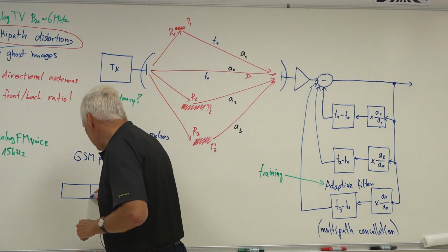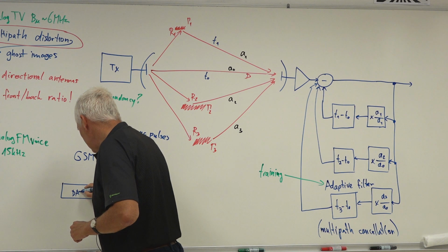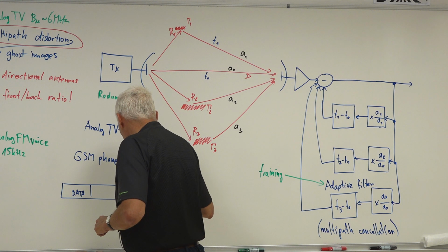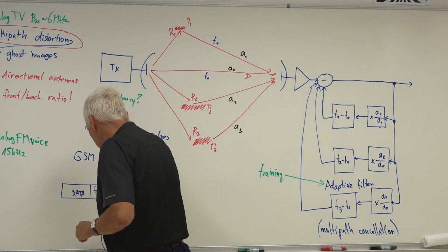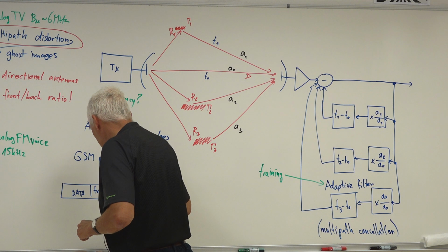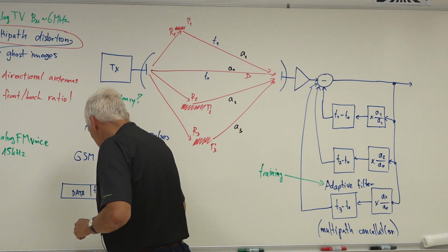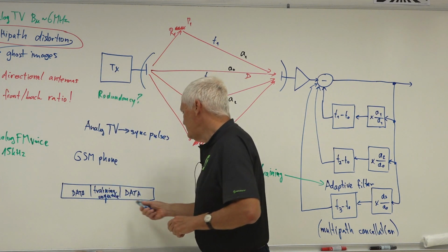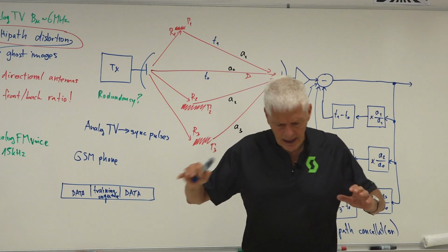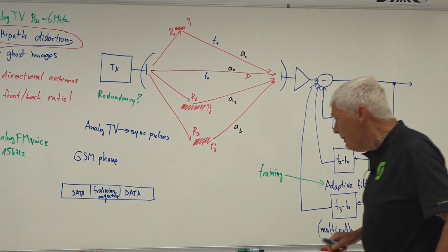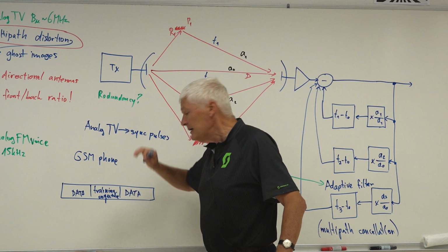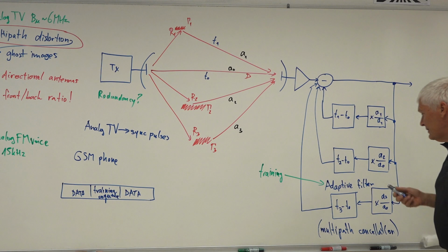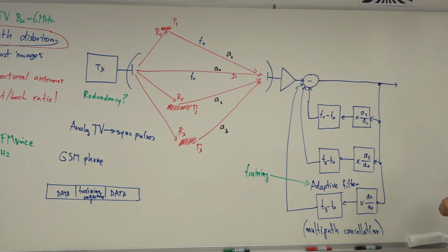The GSM packet had data at the beginning, data at the end, and here in the middle it had a training sequence. So the training sequence was most protected from any kind of interference or packet collisions by putting it just in the middle of the packet, and training the receiver filter to make this solution.